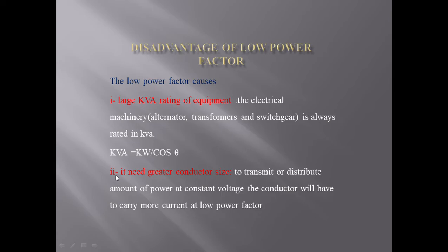Number 2, it needs greater conductor size. To transmit or distribute an amount of power at a constant voltage, the conductor will have to carry more current at a low power factor. So with a low power factor, you need greater conductor size to distribute your power.